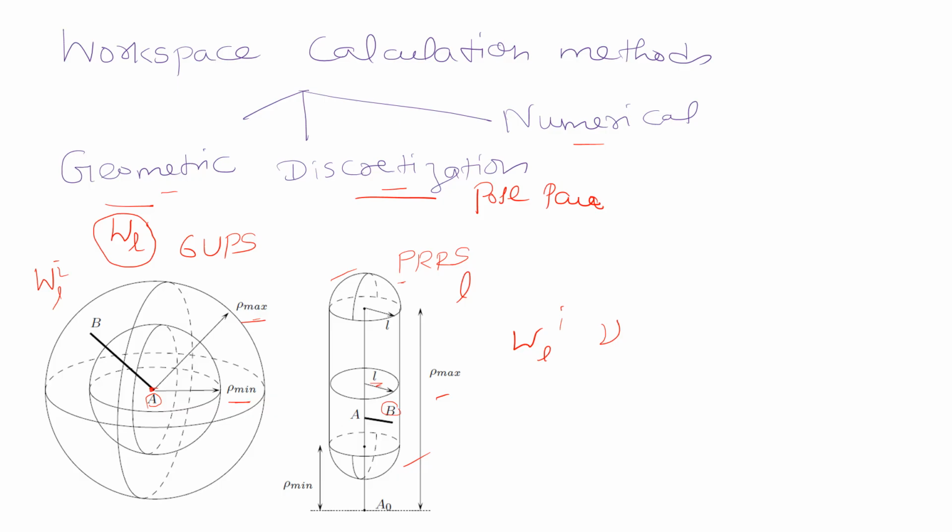The workspace is covered by a regular grid of nodes, either Cartesian or polar, and each node is then tested to see whether it belongs to the workspace or not, right? So the boundary of the workspace is constituted of the set of valid nodes for which at least one close neighbor does not belong to the workspace.